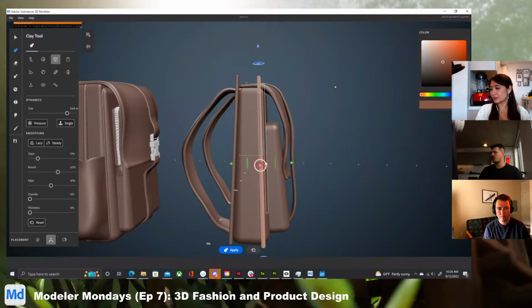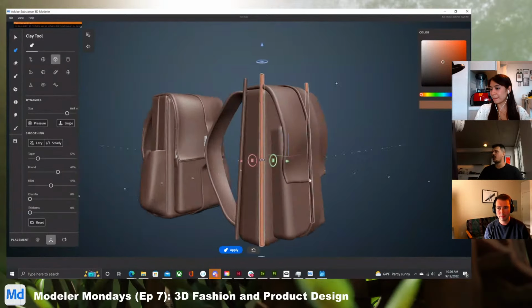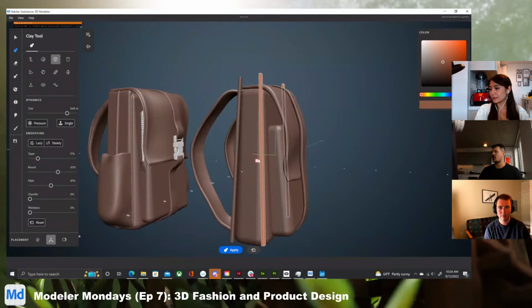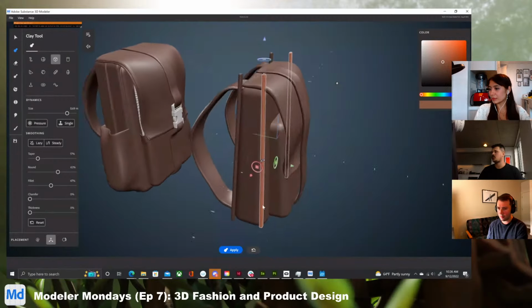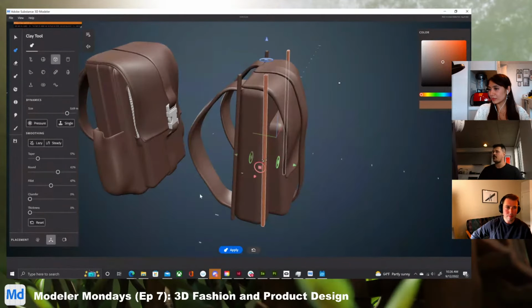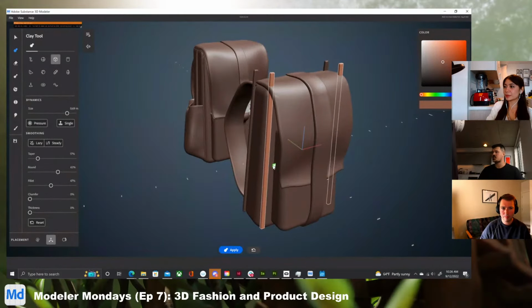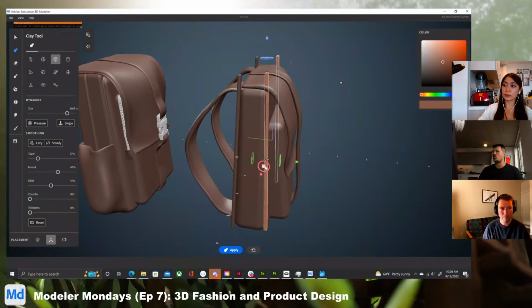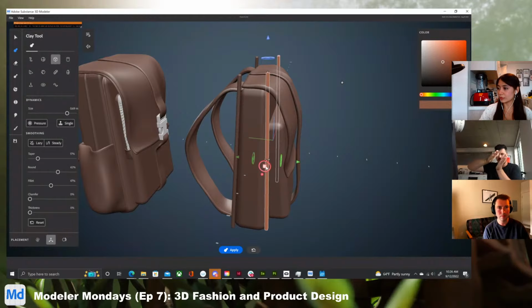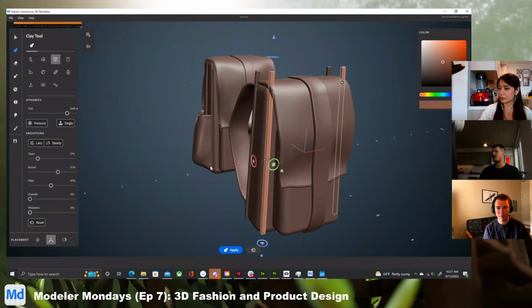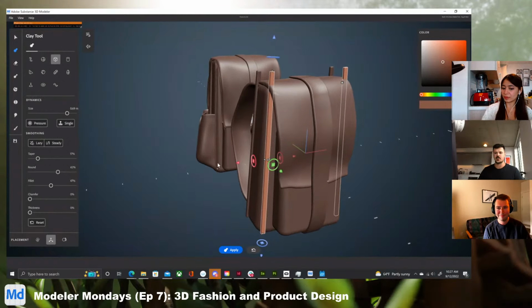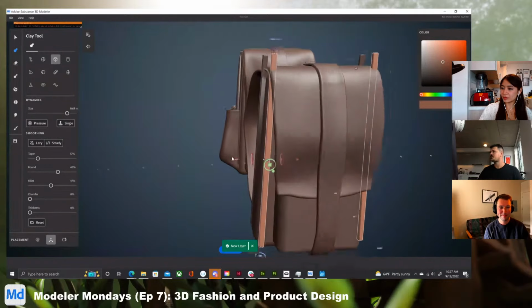Yeah, the warp tool, I go back and forth. Exactly what Dave was saying: when I'm trying to make aggressive changes to a large shape, I'll use the elastic tool. When I want to take a surface and make it thinner, I'll switch to the warp tool, because with the warp tool I can push surfaces and make profiles a little bit thinner, which you'll see in the shoe demo. So I'll go back and forth between the two.